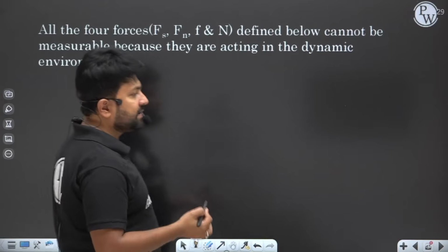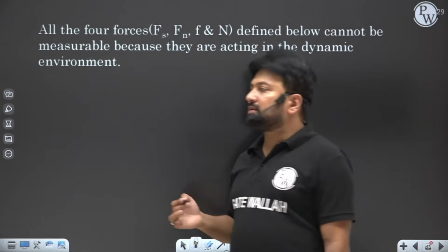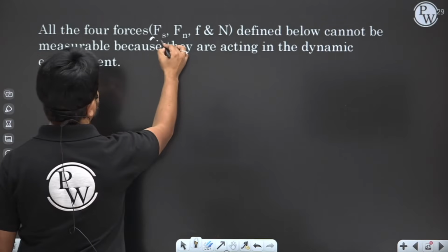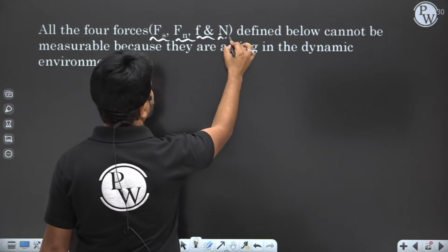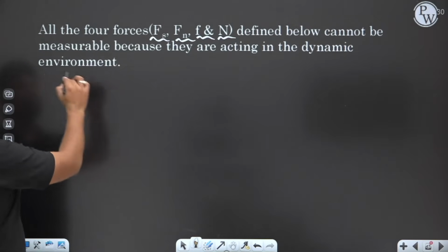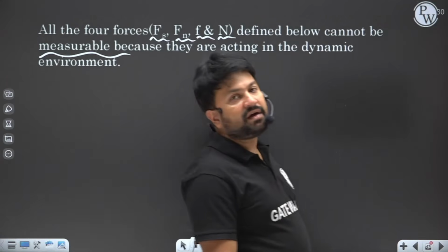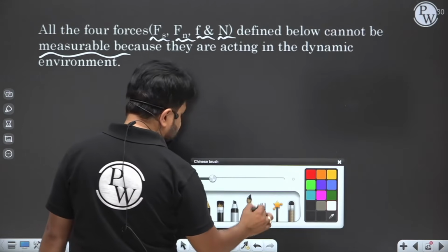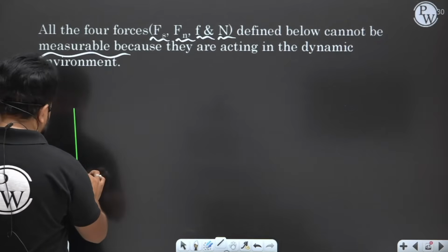When you are doing a cutting operation, four forces come into the picture: the shear force, the normal force, the friction force, and the normal to the friction force. All four forces defined below cannot be measured directly, because they are acting in a dynamic condition. Let me draw a figure so that you can understand.